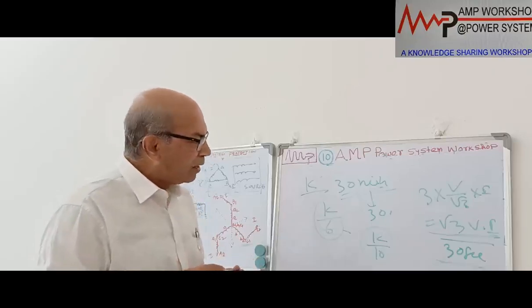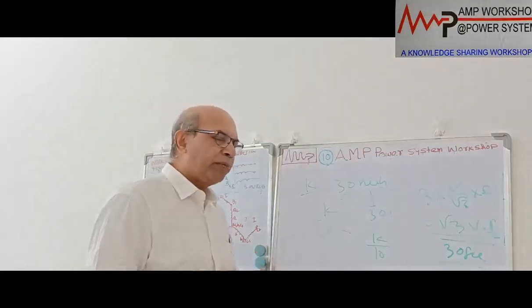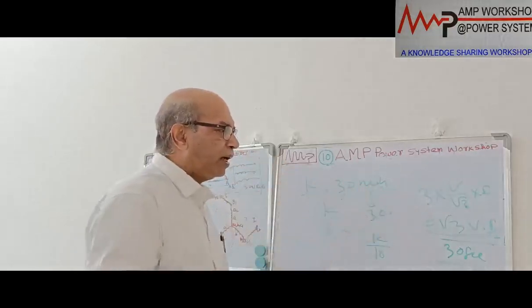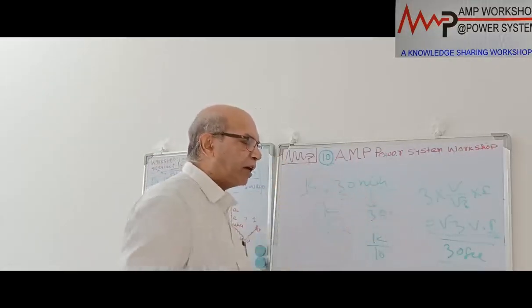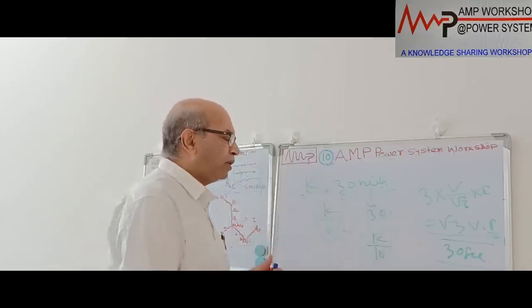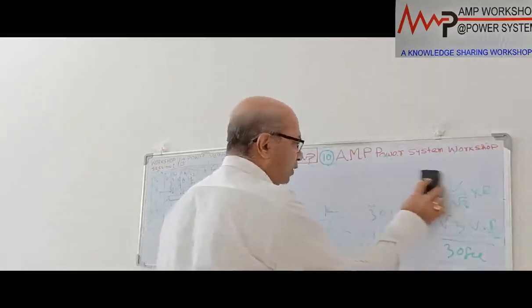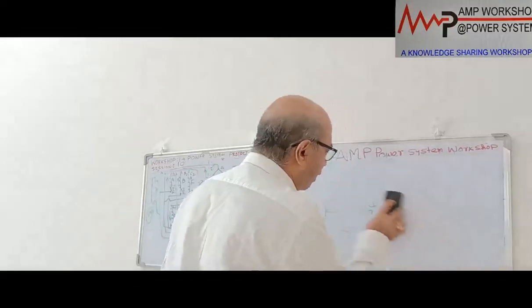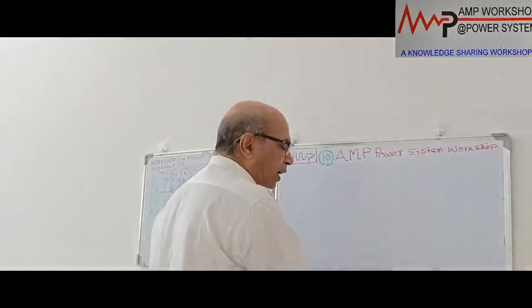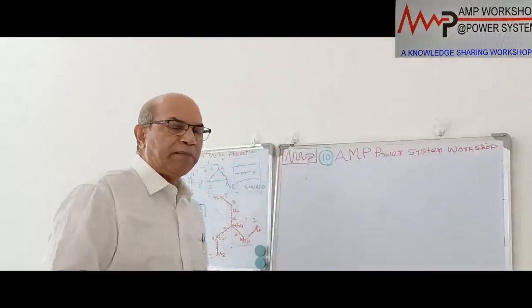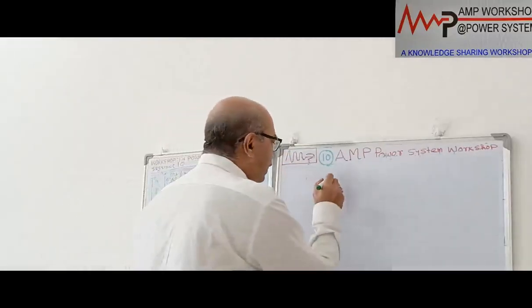Okay. So the grounding transformer rating calculation will be whatever the continuous rating as per the voltage and current calculation is coming, 1/10 of that will be considered as the grounding transformer capacity. Okay, that is the kVA capacity. Now the voltage rating of the grounding transformer, or the insulation grade of the transformer, is to be decided based on the voltage it is getting injected.